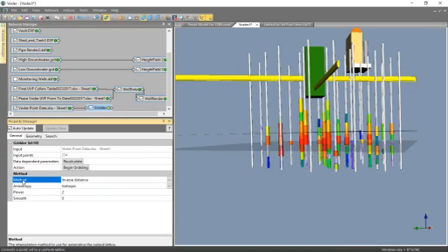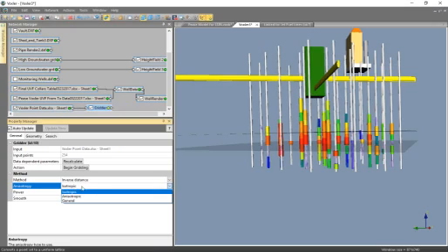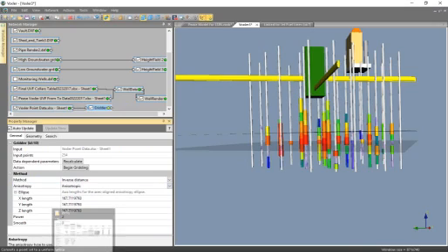So with that gridder module selected, on the General tab here, we can see a few parameters. Steve used inverse distance as his gridding method. And then he changed the anisotropy to anisotropic, where he changed the x length to 55, the y length to 55, and of course this refers to units.